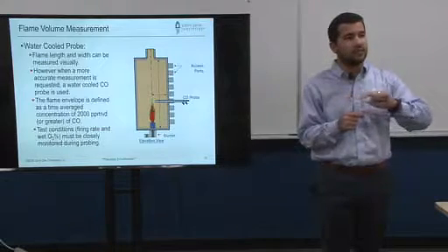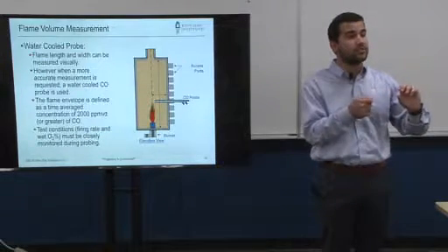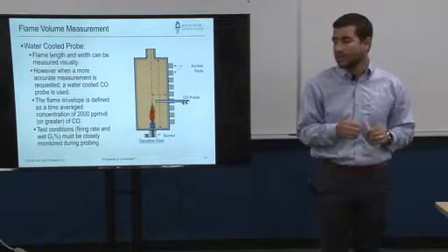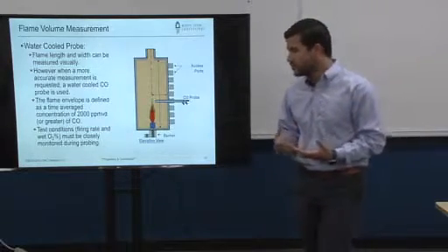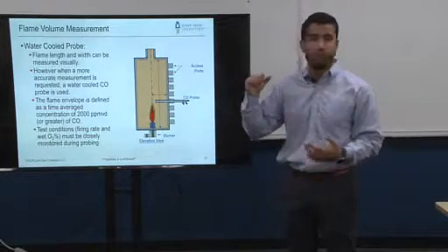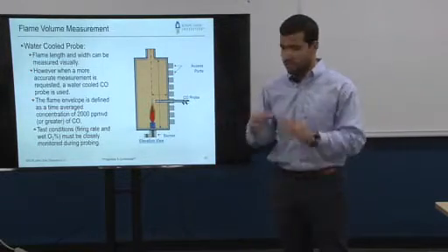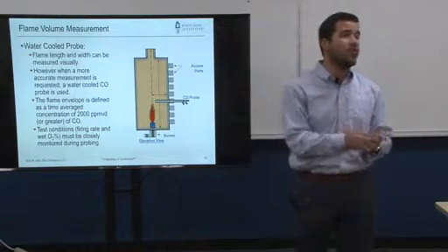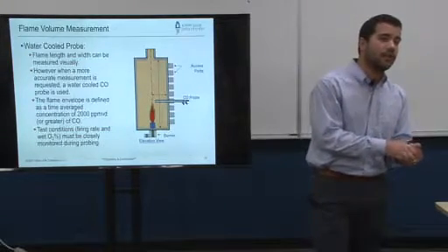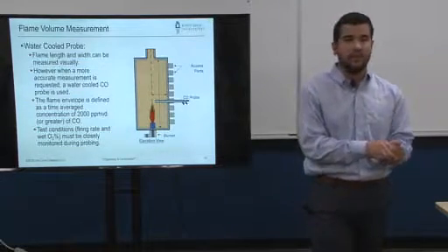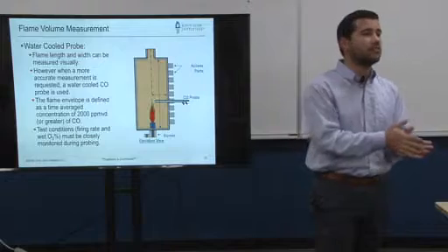And through the center of that probe you have suction, and you take out a sample at a given point. All our test furnaces are equipped with ports where you stick this probe, and you place the probe in a known location and measure the CO at that particular location. According to API, the flame boundary is defined at 2,000 ppm.